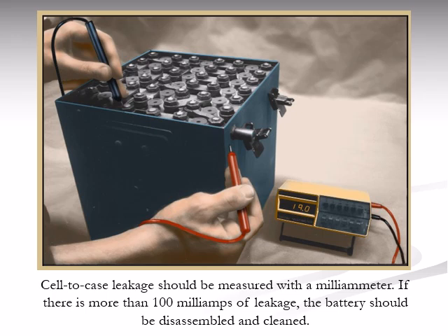A reading above 100 milliamps is considered excessive. Such leakage can cause electrical faults, compromise safety, and lead to corrosion or performance issues.